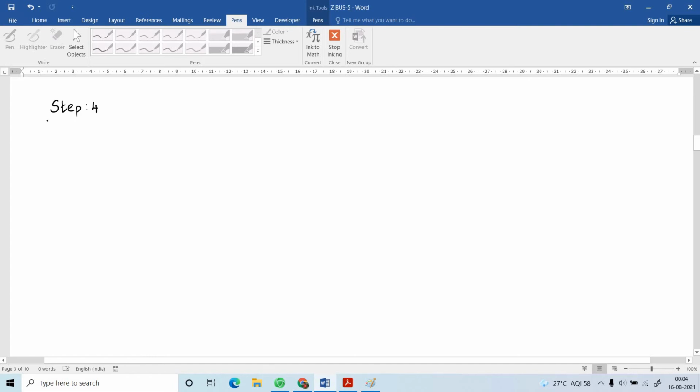First of all, I am going to redraw the power system. Already 3 steps are over and we have used 3 impedances already. Now in this step, I am going to add the new impedance as well as the new bus. See, this is the reference bus and this is bus number 1 and this is bus number 2.